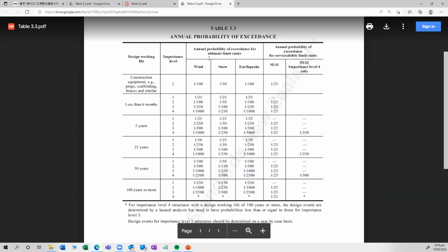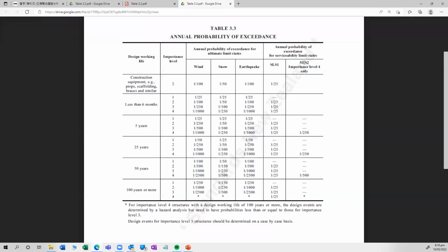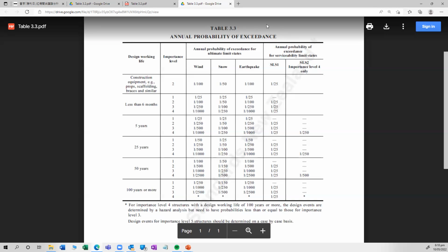So in this case, ultimate limit state, you're designing the building or the members to avoid collapsing under bending or shear. In this one, you're designing for serviceability, so that the building doesn't deform too much. It doesn't mean it'll fall over, but you don't want something to tilt over at an angle too much, or if you've got a beam, you don't want it sagging too much.